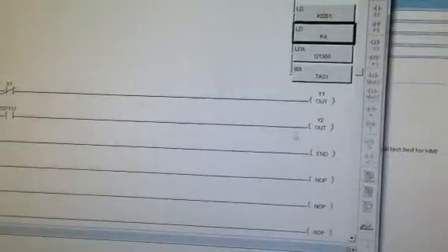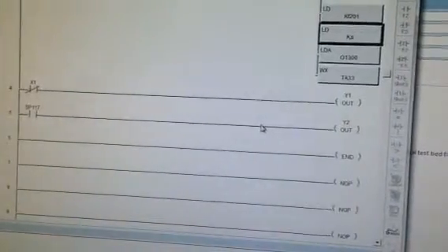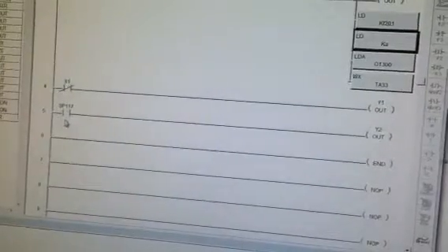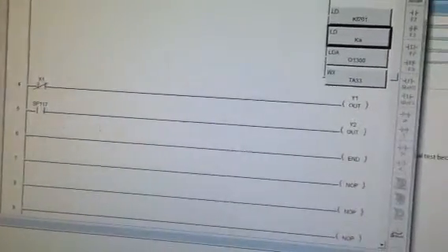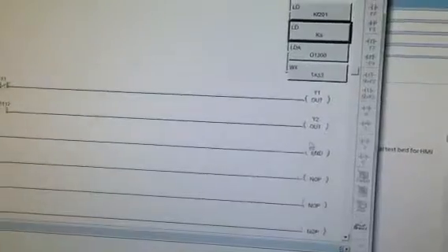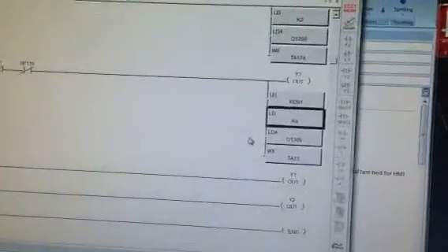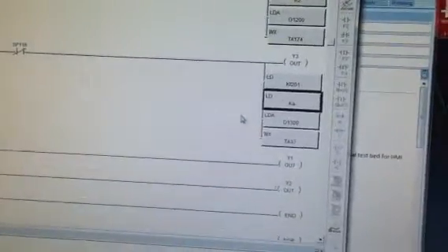And then I've just got a couple other things of interest here. SB117 is an internal register that tells me if I have a Modbus error. That will turn on the LED Y2, and that's useful for diagnostics. I've run into a few problems today that had to be solved, and without that LED I would not have known where the problem is.